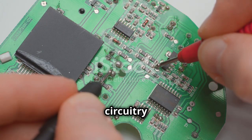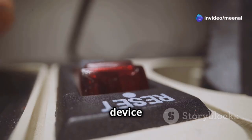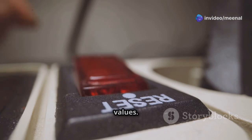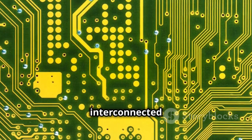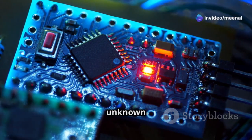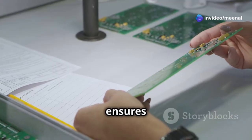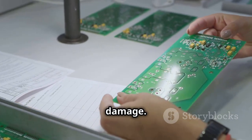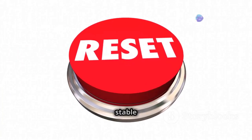Before diving into reset circuitry design, let's understand its importance. Reset circuitry forces a device into a known initial state, ensuring all components are initialized to their default values. Electronic devices are complex systems with numerous interconnected components. When power is first applied, these components might be in an unknown state, leading to erratic behavior. Reset circuitry ensures all components start from a stable state, preventing errors or damage. It also acts as a safety mechanism during operation, bringing the system back to a stable state if needed.